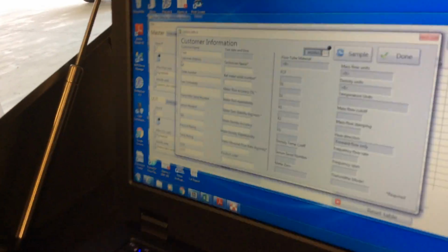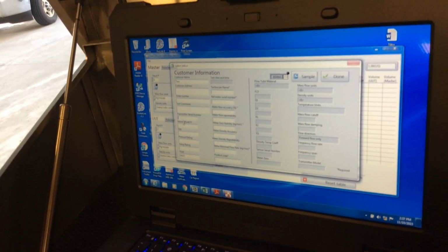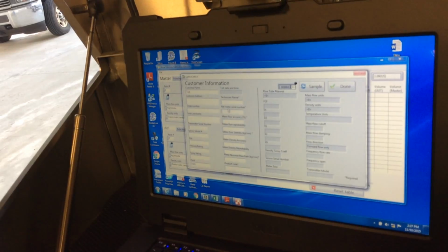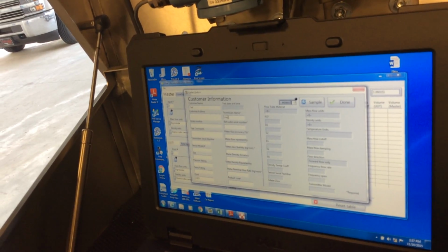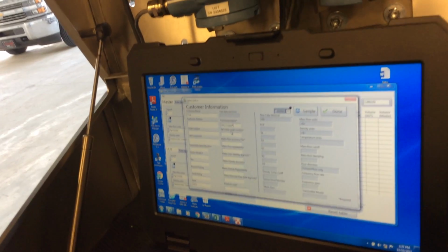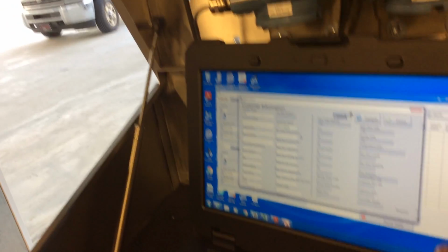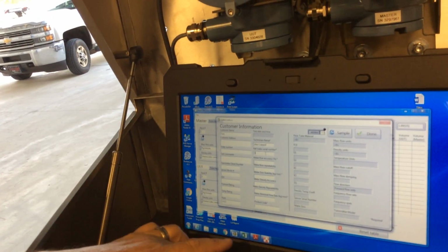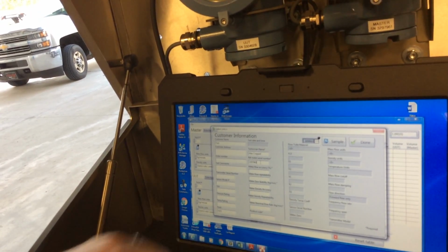It was this reflection. But you want to put in whatever your customer's name is, your transmitter serial number, model number, that kind of thing, and your technician name. But here are some numbers that are required. You have to have your reference meter serial number, with the asterisks. That's correct, and you have that here. So that's your reference meter: 3297961 on this particular one.